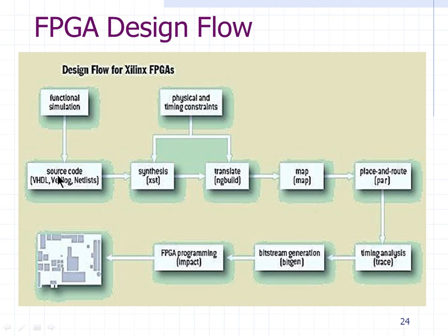Once you write your Verilog design, you will have to test it. So you create something called a test bench, also in Verilog. The design is in Verilog, the test bench is in Verilog. The design and the test bench will be simulated for functionality. Simulation is a software-level verification. You verify whether the functionality of your design matches the design specification given.